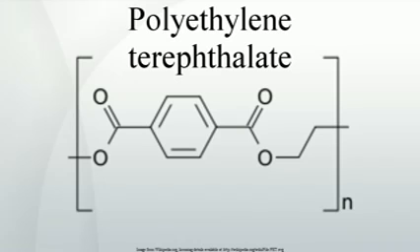Since this building block is much larger, with 6 additional carbon atoms, than the ethylene glycol unit it replaces, it does not fit in with the neighboring chains the way an ethylene glycol unit would. This interferes with crystallization and lowers the polymer's melting temperature. In general, such PET is known as PETG, polyethylene terephthalate glycol modified.